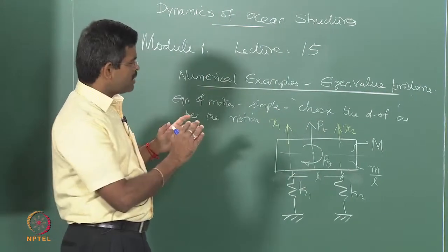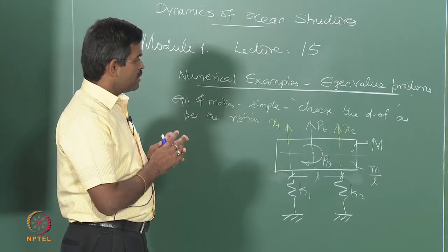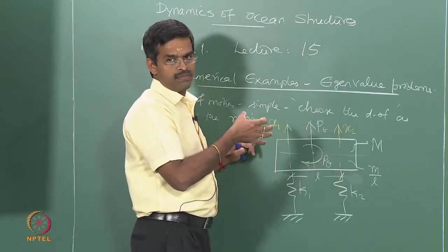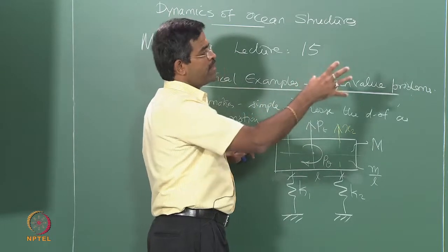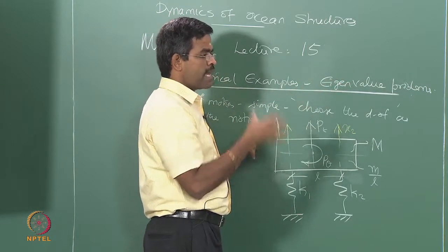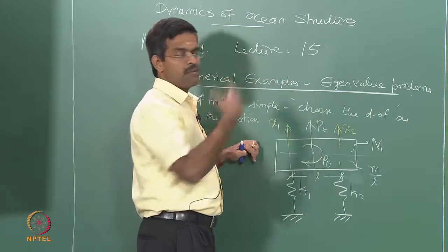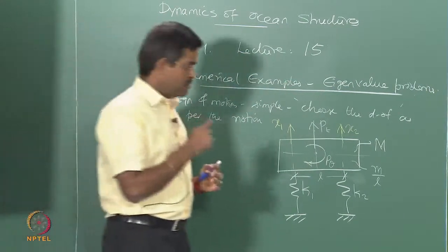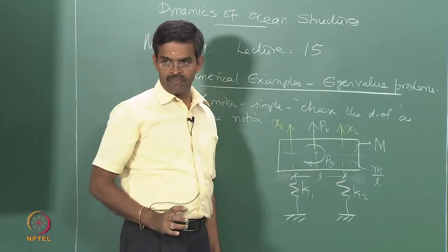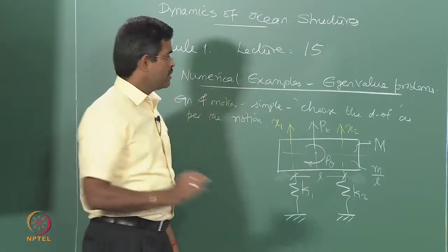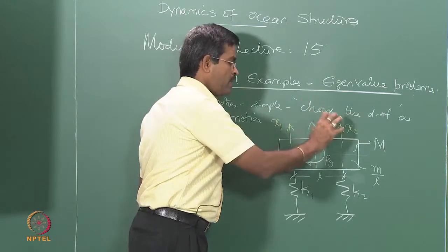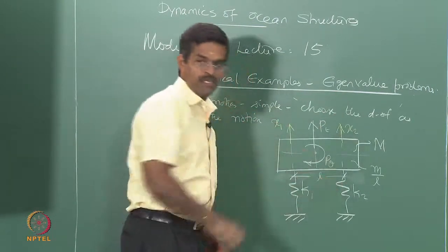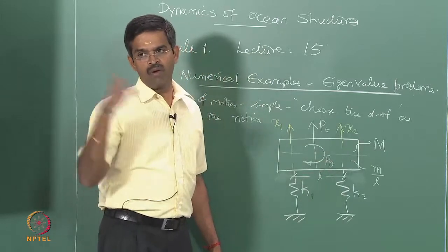So, from a first hand understanding, we will know that if you select the degrees of freedom at the point where the mass is lumped, you experienced the mass matrix to be diagonally dominant and the off diagonal elements were becoming 0. So, you can expect that in the stiffness matrix now. It is a very simple thumb rule. If your degrees of freedom align either with the lumped mass points or with the stiffness points, either of them will have off diagonal terms 0.